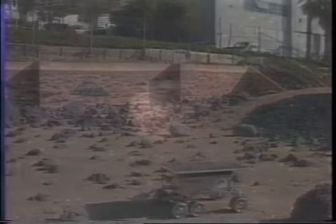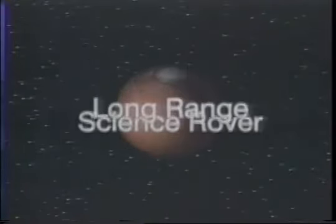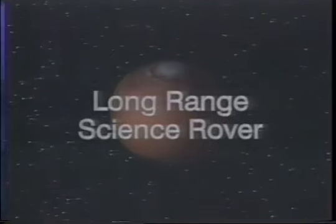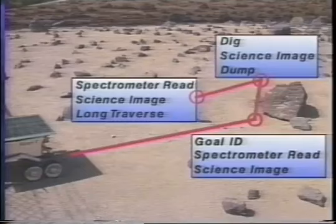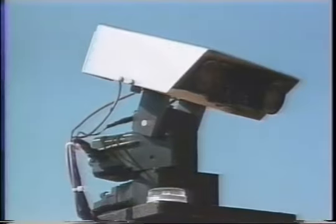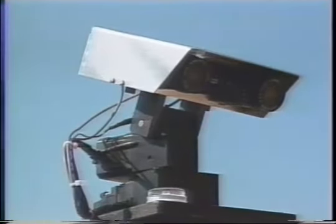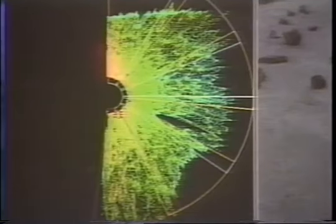The JPL Long Range Science Rover team has developed new technologies which enable future long-range rover missions to Mars. A single uplink command cycle to the Rocky 7 rover in the JPL Mars yard will demonstrate the current rover technology. A 180-degree panoramic image set was taken by cameras on the simulated lander and downlinked in the previous command cycle. A terrain map was generated, which maps image pixel coordinates to 3D terrain locations.